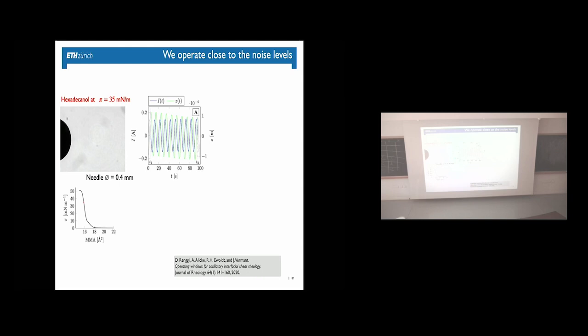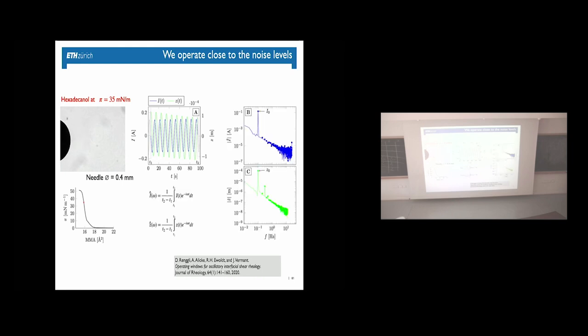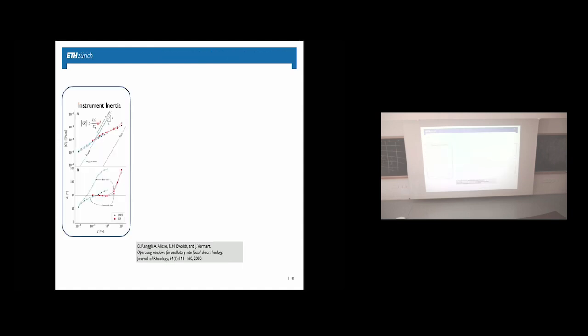Okay? So we can take the signals, stress, in this case current through our coils, position and strain, and then we can Fourier transform them, and you can decide to have a certain noise level that you say, okay, now I know that I'm no longer within the noise. We take 10%, but okay, you could take 5. As long as you say what you're doing, this is absolutely fine. Background, and you say, okay, this is the noise floor, and you can really say, when I'm above the noise floor, I accept this. You can also do this for rotational instruments. They don't always do it properly, the TA Instruments and Anton Paars of this world, but some do a reasonable analysis of this.